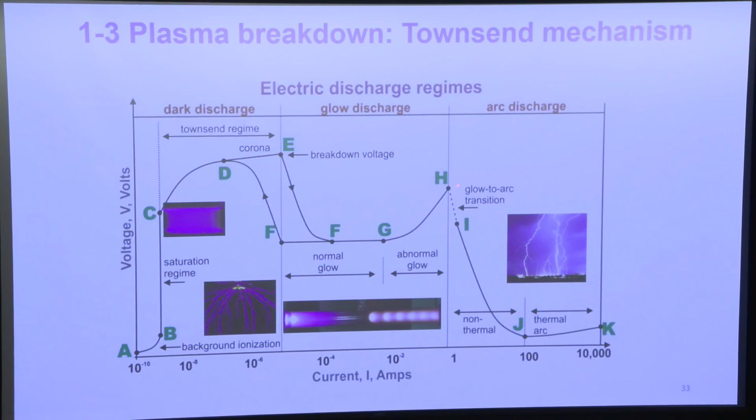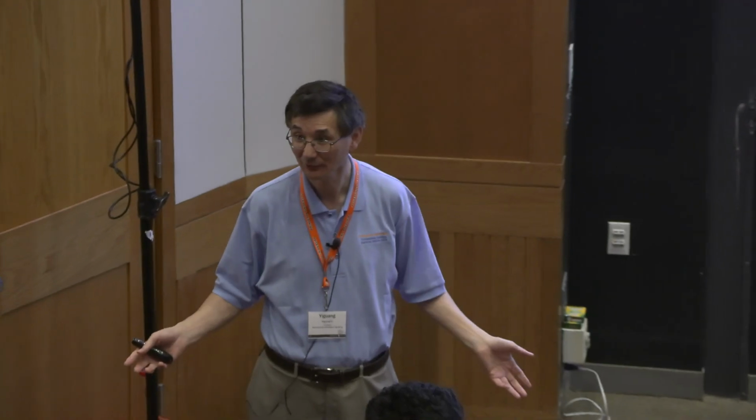So once the voltage becomes so high, suddenly you generate an arc that starts to form like this, and eventually becomes strong. Once the arc is formed, they generate enormous thermalization. So here the ions and electrons are generated by what? By collisional ionization. Here the electrons are generated by what? From the surface, cathode electron emission, secondary electron emission. Here the electrons are generated by what? By thermalization. Because the gas becomes so hot, the electron is just stripped by itself without electron collision, right?